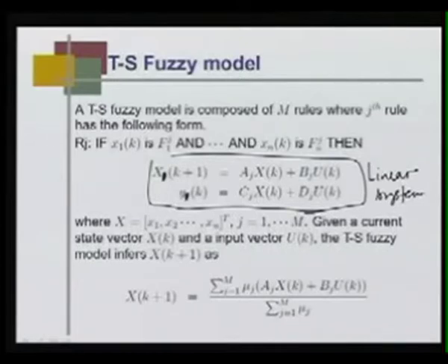You know, this membership function normally is derived either as the minimum of the membership functions associated with F 1 j, F 2 j until F n j, or the product of them. We can select any one of them, but whatever it is, that is mu j. You select one principle and then find out what is mu j, the membership function inferred for the rule. Okay. See, the membership function is always given a crisp value x 1 k, I know what is the membership function from F 1 j. Similarly, given a crisp value x n k, the membership function associated with x n k is computed from F n j, but the membership function of the rule is mu j, and this mu j is either the minimum of these computed membership functions, or mu 1 of x 1 k into mu 2 of x 2 k until mu n of x n k is mu j. We can do that also.